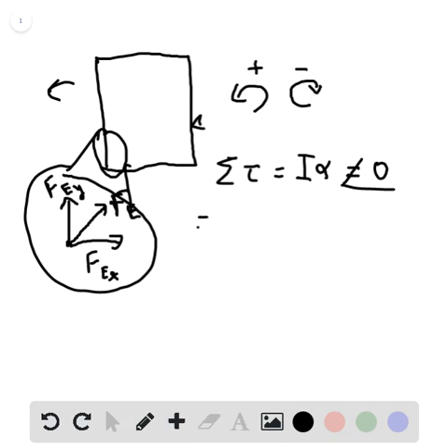So for the sum of the torques, we have a torque produced from the force of the air pushing leftwards. And since we have counterclockwise as positive, anything going in that direction, like the left direction, is going to be positive. So let's just write a general formula for torque first, real quick. Torque is normally defined, the vector torque is defined by position crossed with force.